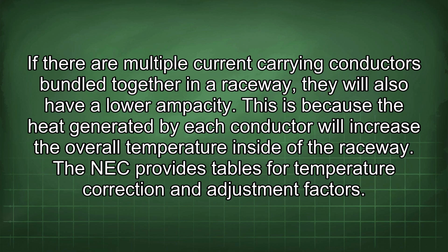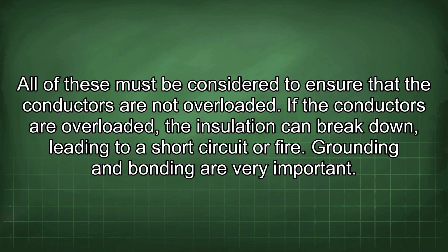This is because the heat generated by each conductor will increase the overall temperature inside of the raceway. The NEC provides tables for temperature correction and adjustment factors. All of these must be considered to ensure that the conductors are not overloaded. If the conductors are overloaded, the insulation can break down, leading to a short circuit or fire.